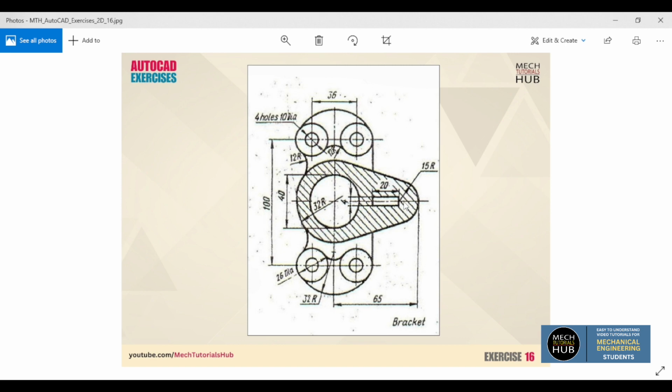Now as this sketch is symmetrical with respect to a horizontal line, I can create the bottom half, then I can reflect it, or else I can do mirroring. Reflection is nothing but mirroring, or else the top half can be created and mirrored, anything is fine. So to save time and use the tools properly, I just create one half, and the other half I'll just mirror. Okay, let me start with a vertical line followed by a horizontal.